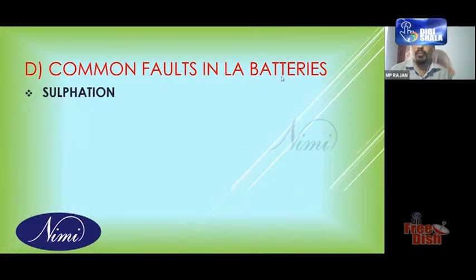अगर खराब हो गया तो आपको बैटरी में ज्यादा ख्याल रखना पड़ेगा. So बैटरी में क्या क्या फॉल्ट नॉर्मली होती है, थोड़ा बहुत आपको आइडिया होना चाहिए. तो सल्फेशन का मतलब है, आपने देखा है lead peroxide and spongy lead are becoming lead sulfate during discharging. अगर आपका बैटरी ज्यादा टाइम डिस्चार्ज कंडीशन में रखा है, आपका बैटरी में लेड सल्फेट बन जाएगा. लेड सल्फेट धीरे धीरे, if you are not charging, that will become a solid concrete type material.